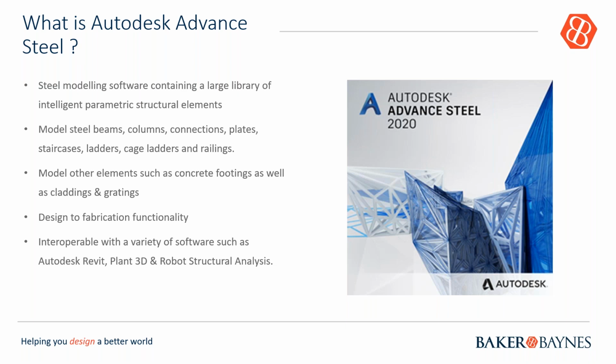Also, the cool thing here is the design to fabrication functionality. What I mean by that is if you do the steel connections and stuff like that in the software, you can automate the drawings, generate them, and you can actually output that to the steel cutting machines because you've got a .nc export as well as a DXF export. So it can be read by the machine and cut accordingly. So really, really end-to-end functionality.